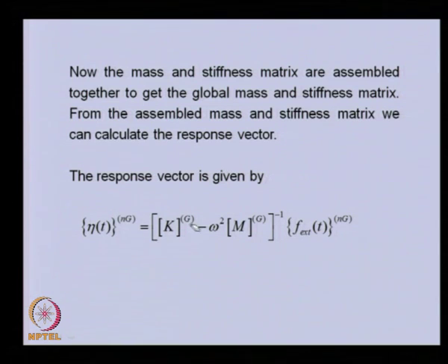This also we discussed earlier, because there is a forced vibration and the main forcing is unbalance. So, we expect this omega will be the spin speed of the rotor, and this is the unbalanced force. So, this we obtain by the global equation of motion after application of the boundary condition. So, this equation can be used to obtain the response.